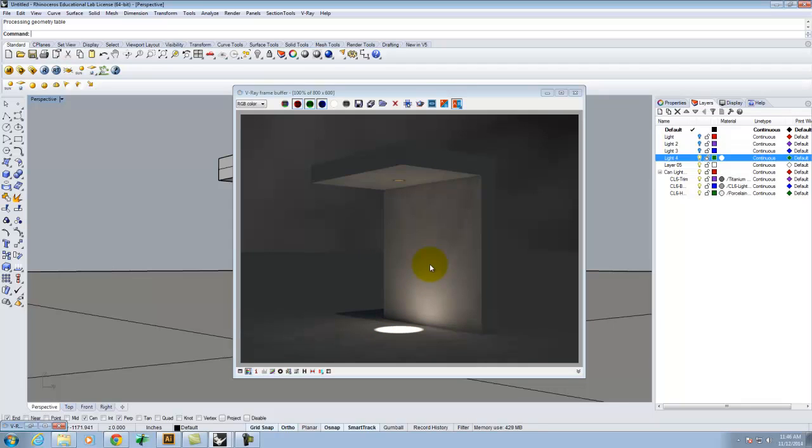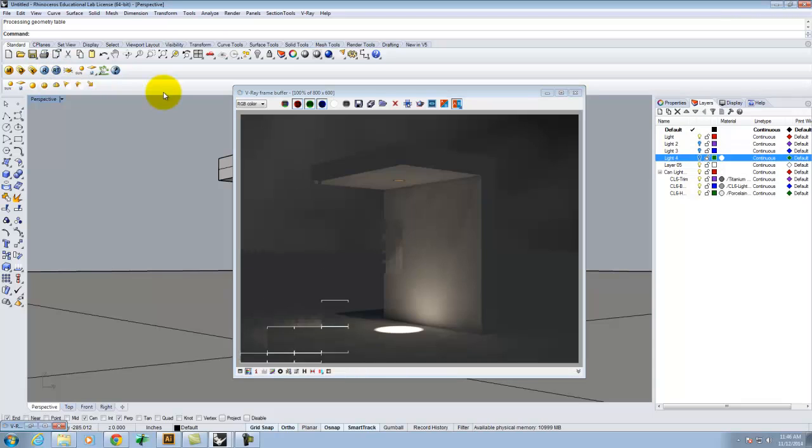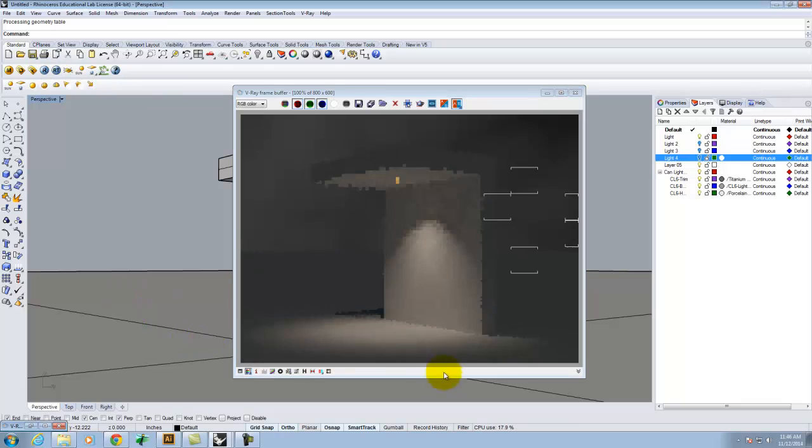And that's part of what makes V-Ray a really good rendering engine, is it calculates those reflections for us, okay? So in reality, this is like what a stage lighting would be, where you have a true spotlight, right? We're using the same spotlight, but we're changing the settings enough so that instead of getting that spotlight, we're really spreading out the light a great deal, and we're getting a pool of light rather than a direct spot, right?